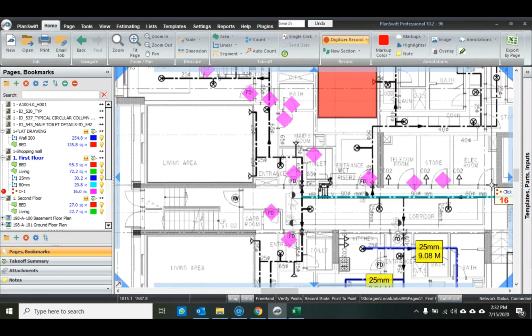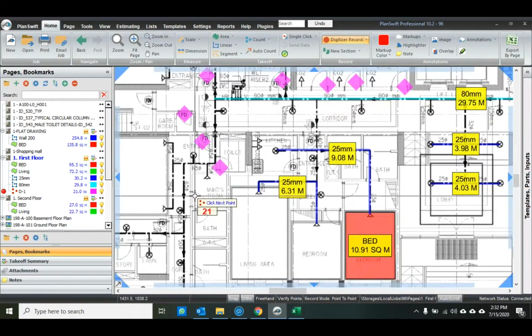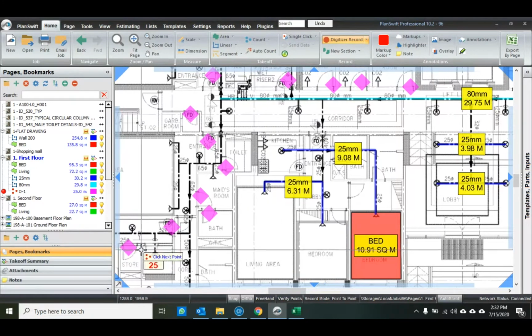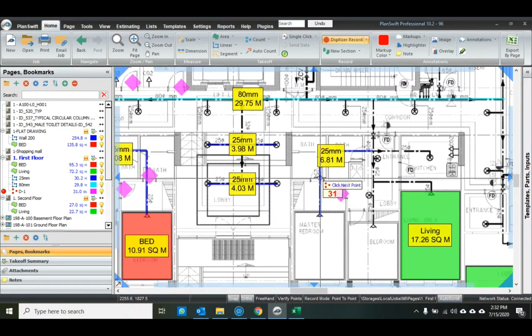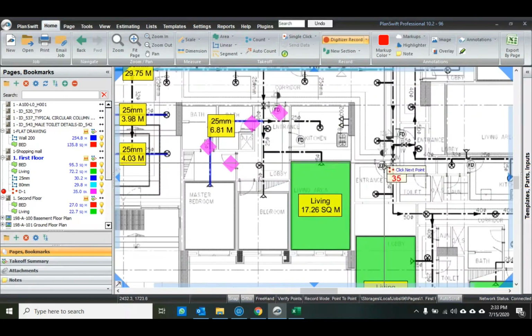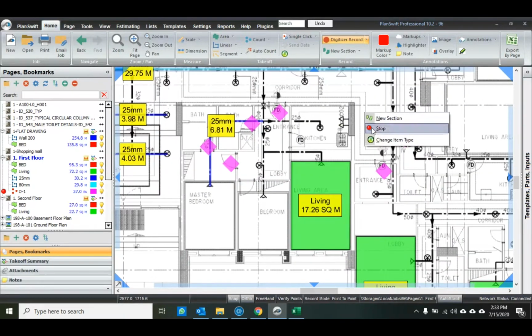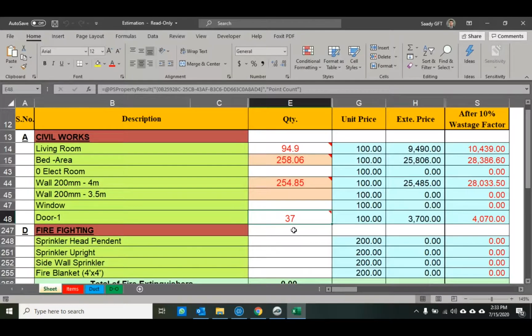And we know that being a quantity surveyor and estimator, the engineers worry about the number. They count two, three times the number because they know one or two mistakes multiplied across a typical floor are going to cost them a big amount. But here we don't need to worry. We don't need to spend extra time. Anytime I can right click and stop. Total numbers are here. So I don't need to remember. Second, I don't need to type. So if I compare with my manual takeoff, these things are already gone.